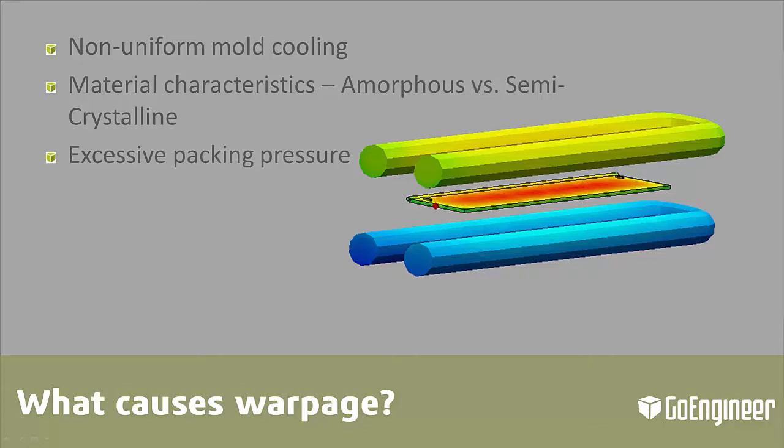These molded-in stresses will lead to warpage as they relieve during the cooling process. Sometimes the stress relief can go on outside the mold for days or even weeks, or if the parts are subject to exterior conditions, they'll also cause those stresses to relieve and warp more. So in the molding process, we want to control the amount of stress we mold into the parts.